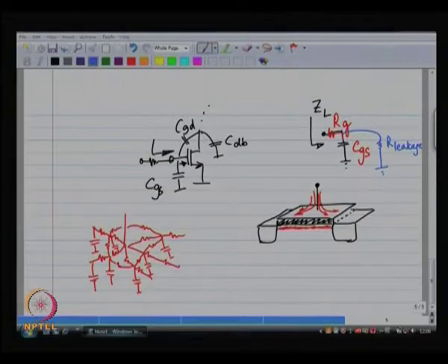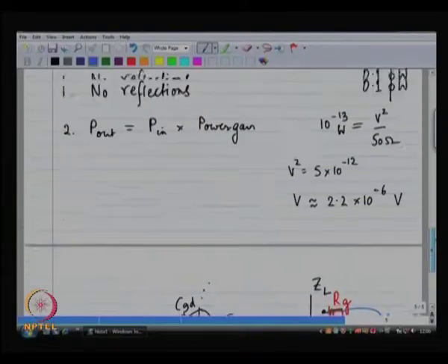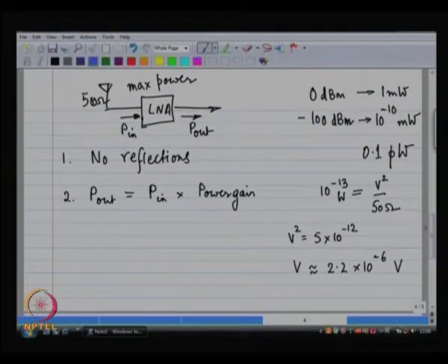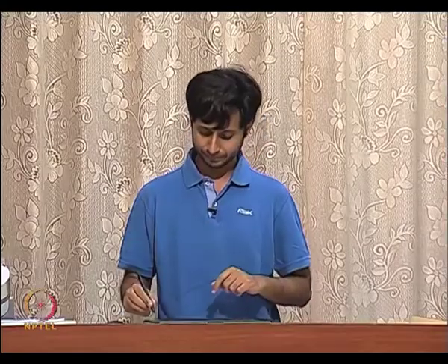For older technologies, our situation is that we have a series gate resistance with the gate to source capacitance or whatsoever. So, this RG is what is burning the power. So, this is where you are delivering the power. Now, next question is, we talked about something called power gain. What on earth is this? I am just giving out terms and you should not blindly accept these terms. What is power gain? What on earth could power gain be?